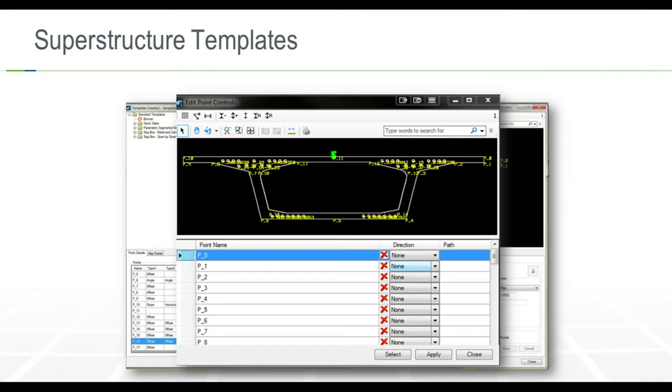For us, that could be, as seen here, having tendons, or things as simple as blisters or deviation blocks inside the tendons. In this case, there's what they call a point control. So I can have a line of geometry at any elevation, and I can use that to control where these tendons are moving. I can pretty quickly generate some tendon geometry just based off of some simple line work that follows the bridge alignment.